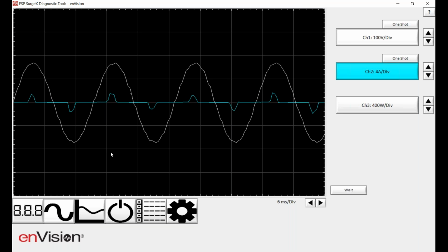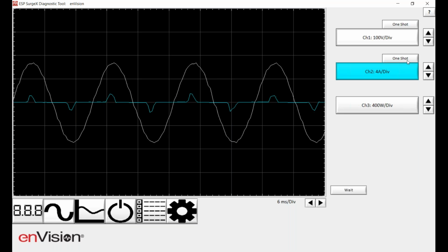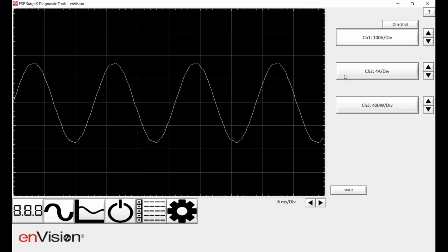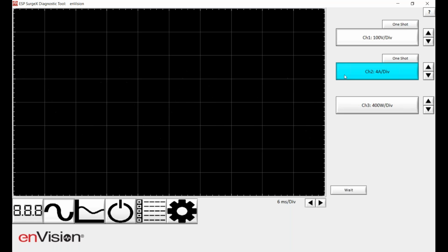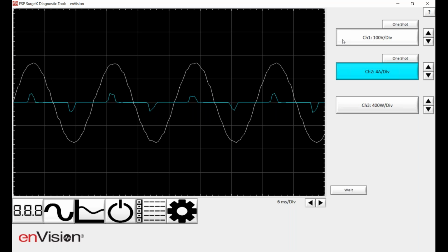Hey Vince, will you do me a favor and click the channel 2 button off? And you should see that the sine wave looks a little bit smoother. That's because our effective bandwidth on this built-in oscilloscope feature is about 4 kilohertz, right? So it's not as good as the $10,000 Tektronix scope we have here in the lab. But if you do the individual channels, and then likewise, Vince, if you'll turn channel 1 off and turn channel 2 on by itself, and you want greater resolution looking at voltage or current by itself, that's what I would recommend. But then if you click them both on, you'll see that now the bandwidth is shared between the two, and that's why the shape is, it's just the way that I'm doing the connecting the dots, as it were. Okay, gotcha. For higher resolution, just look at them independently. Independently, good. That's a good tip.